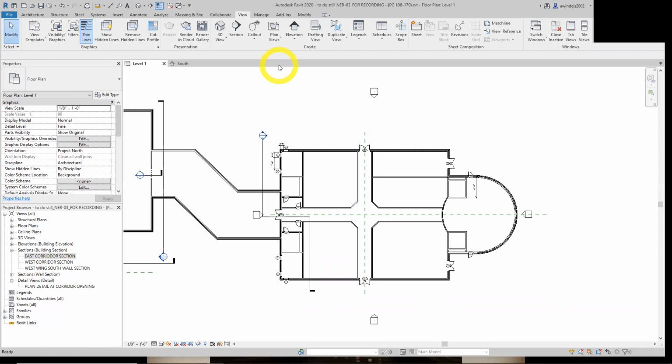Page 148. We're going to start creating callouts. Now, creating a large area model will be a task that every project I've heard and seen, a lot of them will have it. Callouts are very detailed areas. You're going to make areas where there's a lot of additional annotations that are maybe general to, say, a bathroom, or every one of these offices looks like this, or hotel rooms or whatever. That callout area is going to be a focus of detail that gets replicated and designed and on the final sheet. So your callout can be a much bigger scale than, say, this whole floor plan.